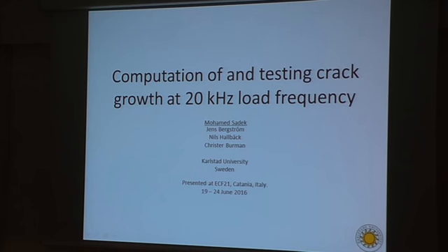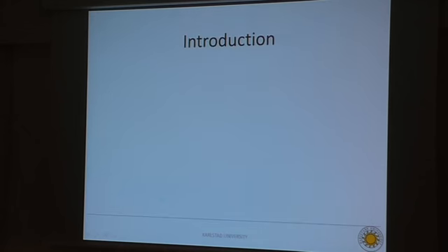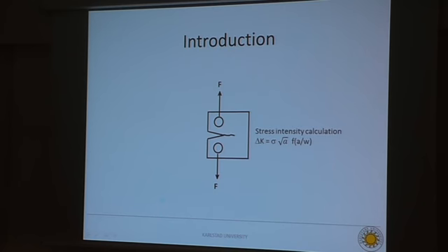I'm here to present my first paper that I wrote about the computation of and testing crack growth rates at 20 kHz load frequency. The computation of the crack growth rates is usually done with the help of the crack growth specimen, like this one, where the stress intensity at the crack tip is calculated by this equation, which depends on the load, crack length, and also the geometry function of the specimen.